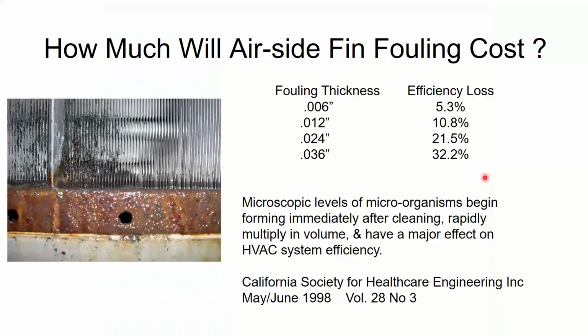In addition to keeping the coil clean, germs are gross. It helps out with two other things. Heat transfer. If I have to cool down my coil, to cool down my fan, to cool down my debris, and then my debris actually cools the air, that's another layer of insulation, if you will, and that takes longer to cool with. And then airflow wise, if there's things on my coil, it restricts airflow as well. So the combination of heat transfer and airflow ends up being pretty substantial.